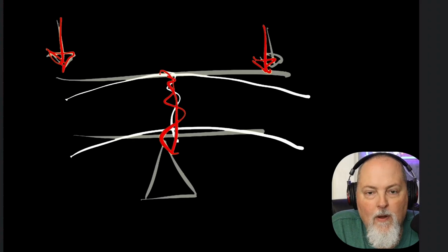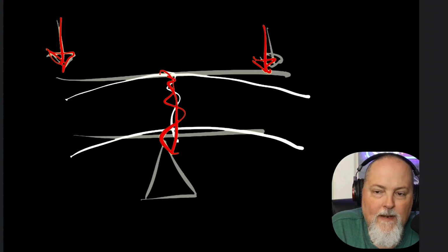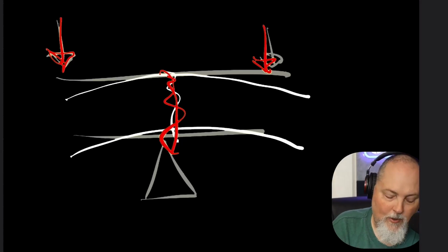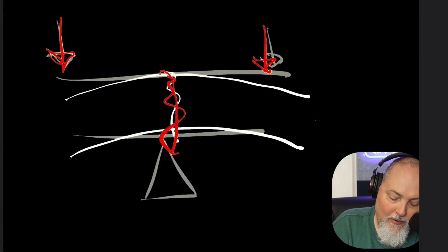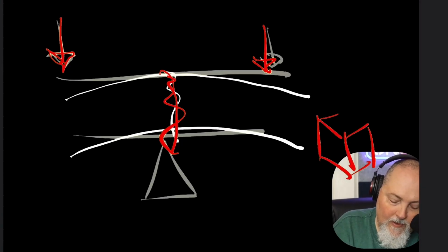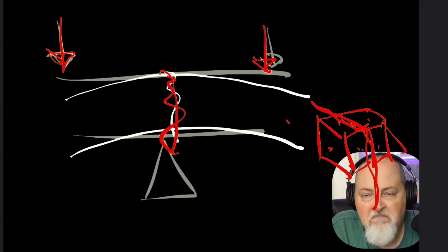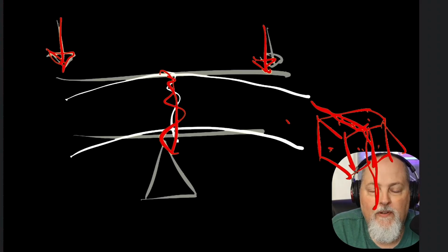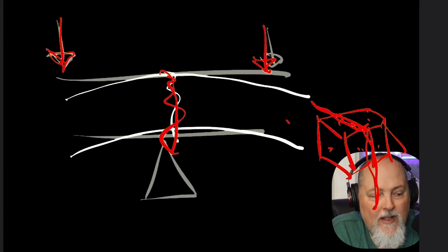But how does it know where to crack? Well, that's the cleavage fracture. It's just fracturing along that atomic crystal structure. So we talked about BCC, FCC, all these different types of atomic structures, right? And this is the FCC where there are atoms in each plane. There's an atom there, and then there's one here. And so cleavage is just shearing at those joinings of the atoms, that crystal structure at the atomic level. So I don't know. Don't get too hung up on cleavage fracture. It's just a rapid, sudden failure.